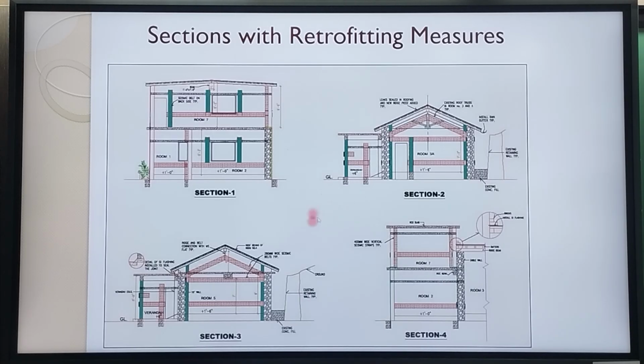This is then further down through the new building. You can see the slab right here as part of the cross section through the last room which had reinforced concrete slab on random rubble masonry, and also we are looking at the passage outside. So this particular junction was a problem. This junction right here was also a problem. That's where the water was leaking.